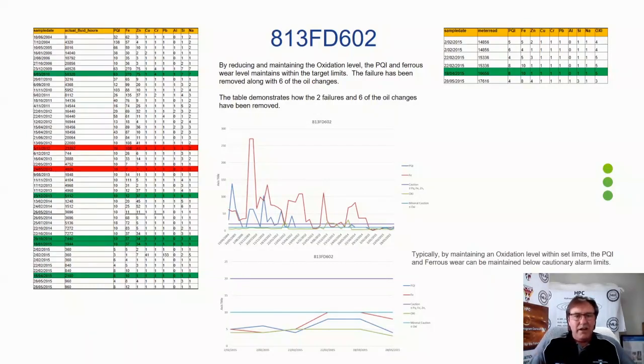We were finding that the dirt ingress on these assets was questionable, whether it was from breathers, from maintenance inspection activities, whether it was soiling arrangements, and until we got to a stage where we were looking at maintaining and doing some engineering improvements, we had to get design life out of this. We had to get oil life extension, right?